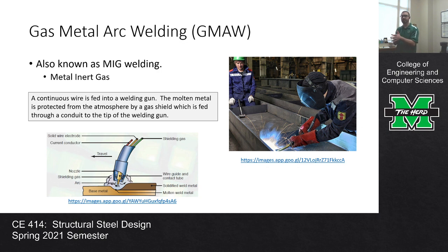In addition to depositing the electrode, the consumable, there's also a connection to a tank of gas. If you ever see a shop MIG welder, not only do you find the wheel of consumable electrode, there's also a big old tank of gas, and that tank of gas is an inert gas. When you hit the trigger, not only are you depositing the electrode, but you're depositing this gas shield as well, and it's doing the same thing that the granular coating on the stick weld is doing. It's shielding the weld from that embrittlement.